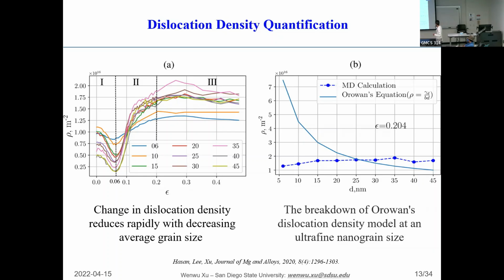And what we really calculated from the molecular dynamics simulation is this dotted dash curve here. You can see when the grain size is smaller than about 20 nanometer, there is a significant divergence between these 2 mechanisms. The analytical equation purely assumes that deformation is caused by dislocation dominated effect, but in our molecular dynamics simulations, this is actually not the case.